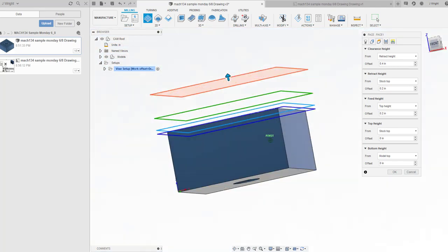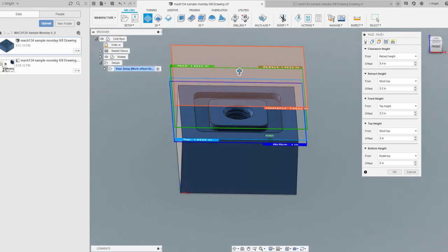It's going to be our clearance heights, and as we come down and start up our program, we're going to come down, wrap it here. So looking for clearance planes, and then you can adjust these as you want.